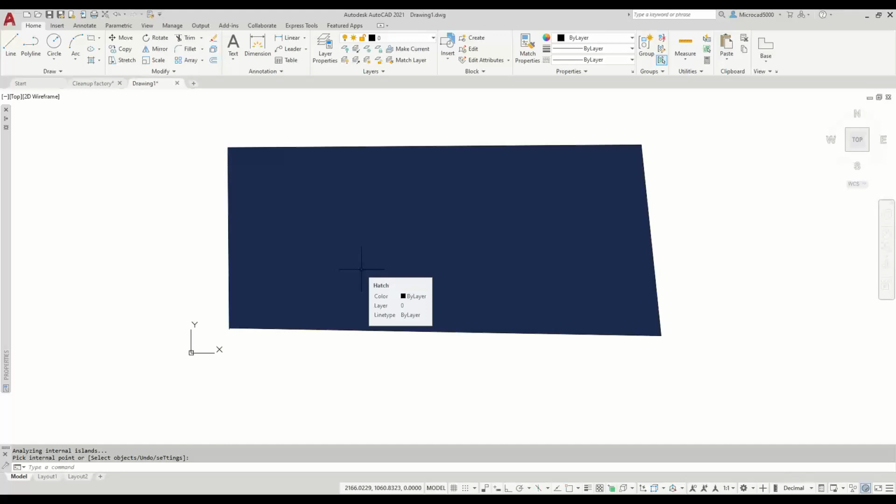If this was a machine tool path and you downloaded that to the machine tool, the tool path would fail because there is physically a break in the coordinates around that boundary. So you would have to find it. However, if that was a hatching for the floor area of a building, or an alarm zone, or a sprinkler area, or just gravel on a roadway, it doesn't really matter if there's a very small break in the corner. No, it doesn't. Get the hatching in, get the drawing out the door. Okay, so watch out for that one.